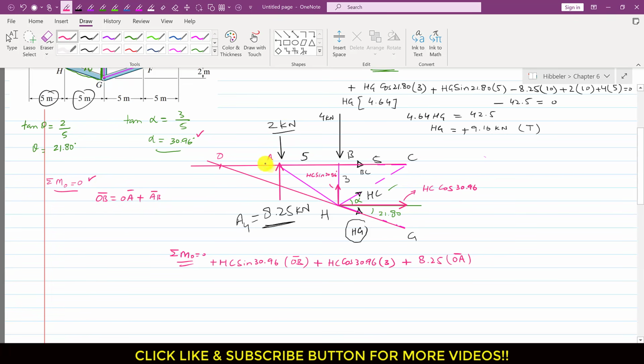Similarly, this 2 kilonewton force is producing the clockwise moment about that point O, so I have to write minus 2, and again the perpendicular distance of this 2 kilonewton force from that point O is this OA, so I have to multiply it with OA.